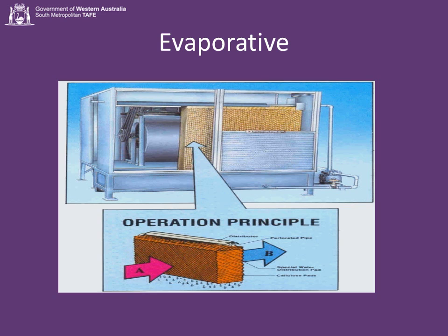This is a very cheap and easy way to cool an area. The downside of it, of course, is that it produces air which is effectively 100% humid. So it produces very humid air inside the space. The other downside is evaporation can only occur if there is somewhere for the water molecule to go to.